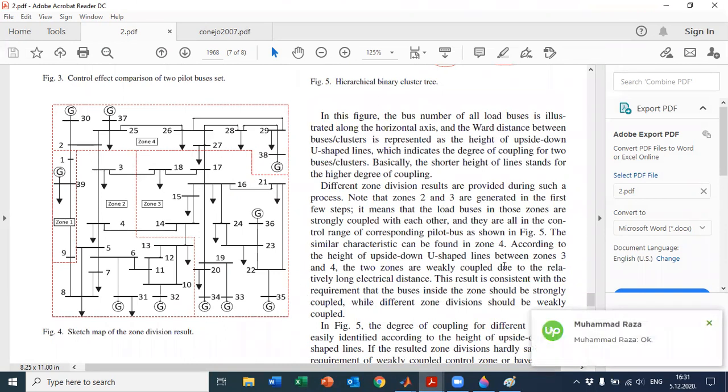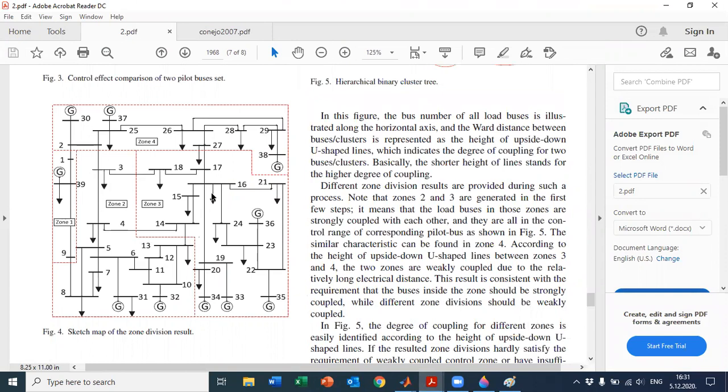We are not doing that, because in the network that they are using, they have generators which have a sufficient regulating range in terms of reactive power. In our case, we are using the PVs. So PVs don't have a wide regulation range in terms of reactive power.